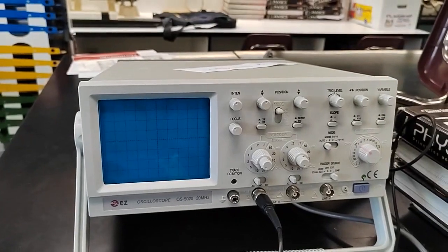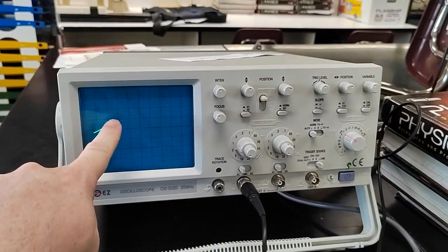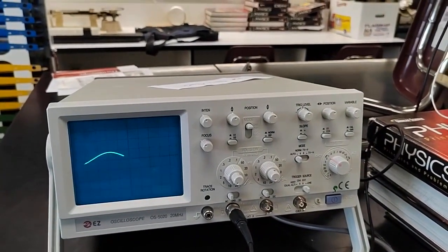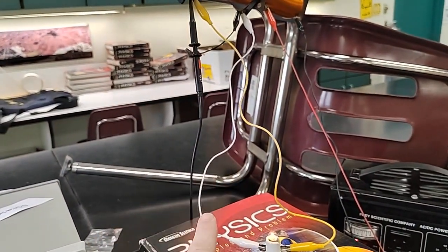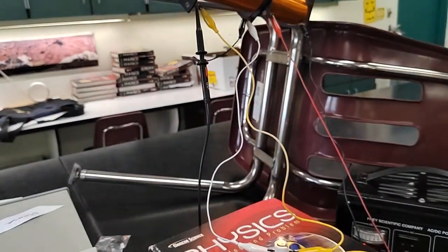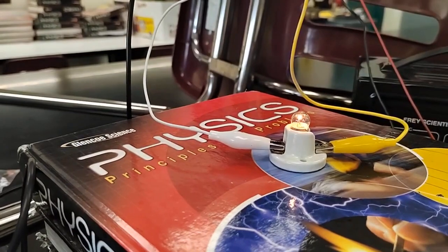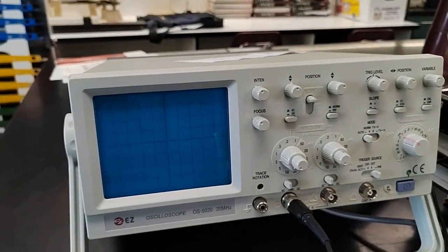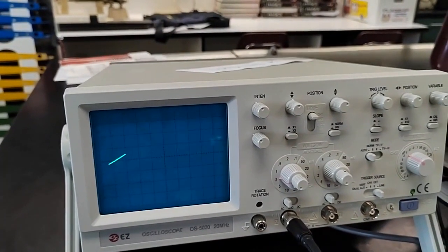But an oscilloscope tells a different story. The potential sometimes is positive and other times is negative. And what that really means is that the current sometimes is flowing into the white wire out of the yellow, and other times it's reversed. In fact, this bulb is turning on and off 60 times every second. And we can see that when we zoom into the millisecond range on this oscilloscope.